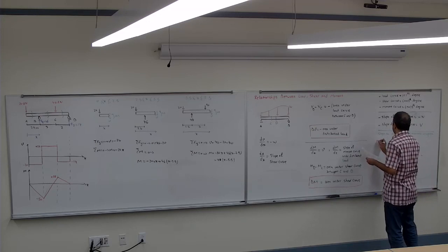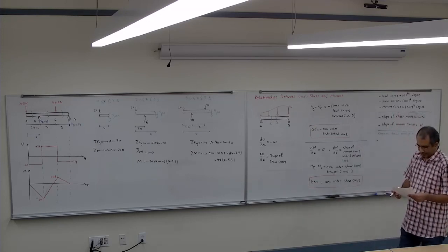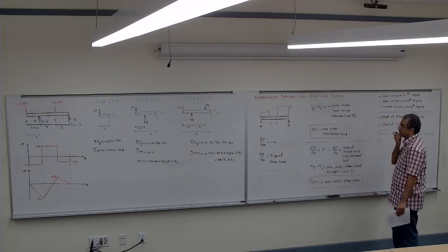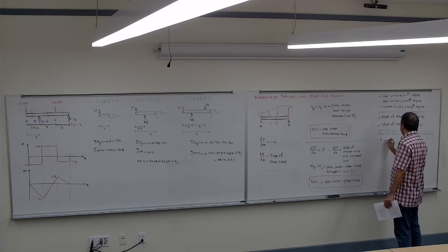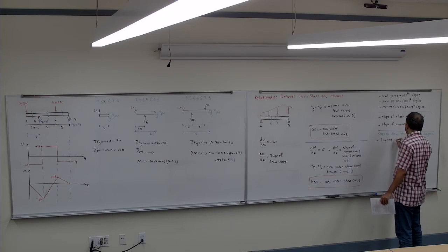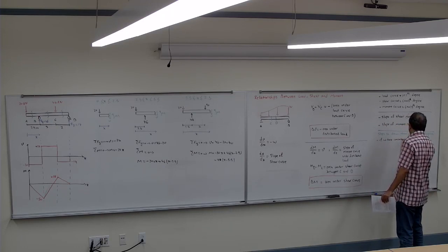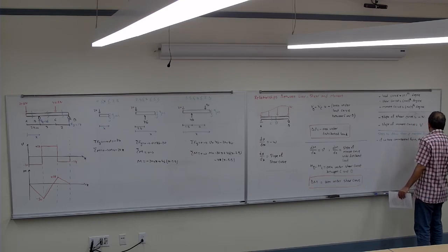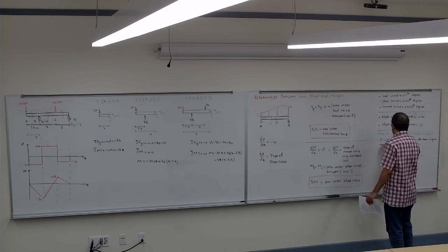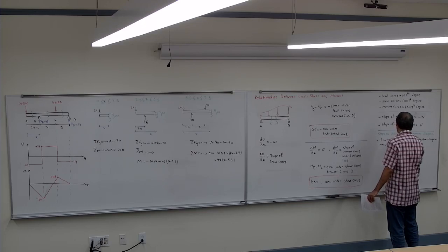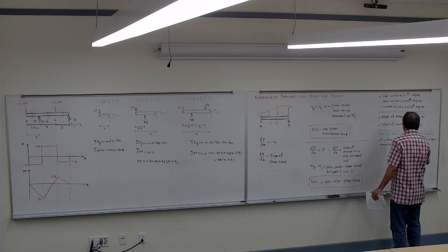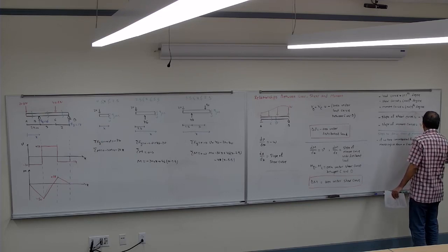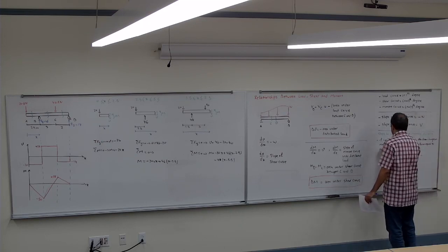So the first step is, if we have a concentrated force, the shear diagram moves up or down in the direction of the force, equal to the magnitude of the force.